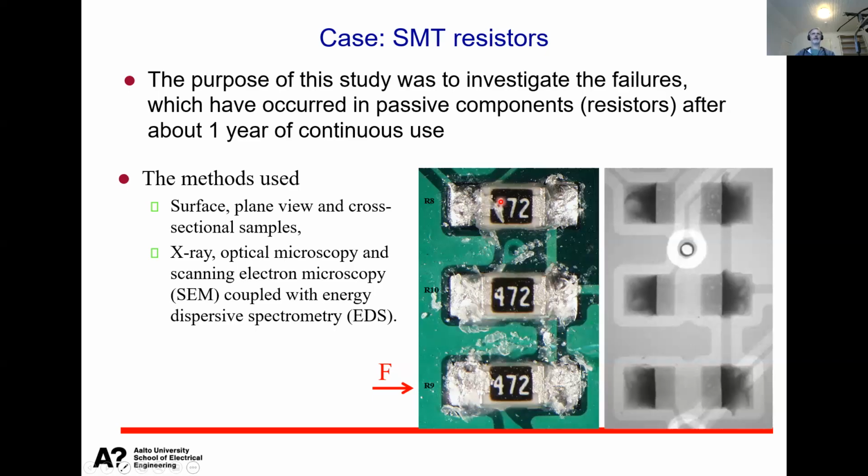So the lifetime target was something like 10 years, and they start seeing failures already after 1 year. And then they had, let's say, pinpointed the problem that these resistors which are shown here, the resistance value for those had increased drastically.